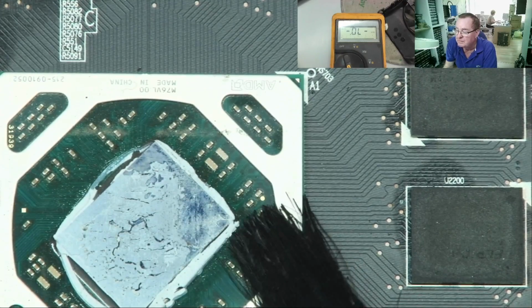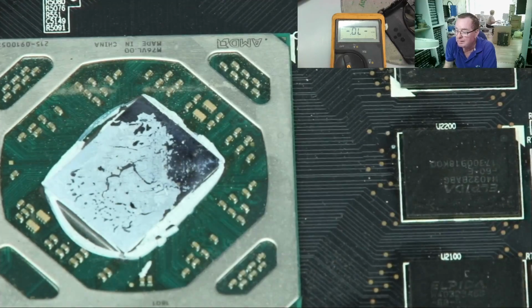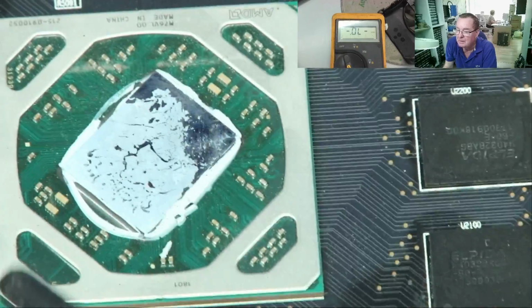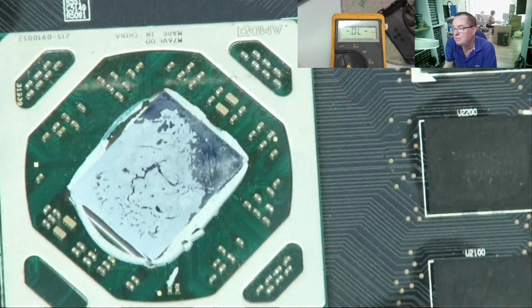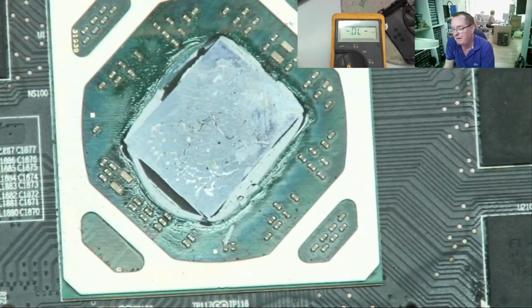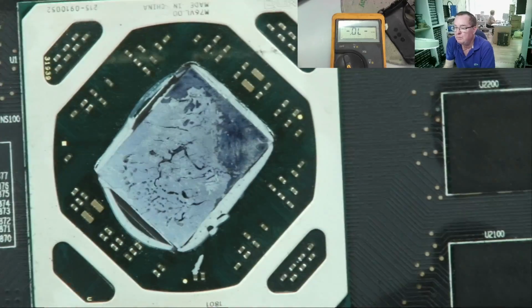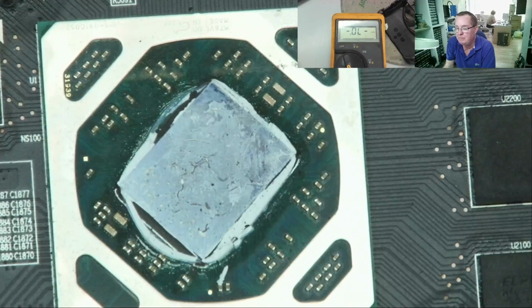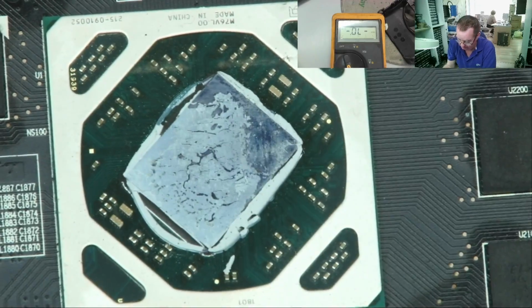It's not flat, you can see it's bubbled, broken away, lifted up a little bit, like domed areas. And if you see that, then you can say, really without any doubt, you've got a duff GPU. Killed by hot air, yeah. Normally, if they fail on their own, they don't fail in that sort of way, not the bubbling.